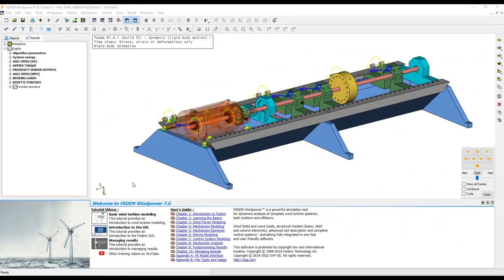When the FEDEM model is benchmarked and optimized for maximum simulation performance, then you can prepare it for digital twin simulations. And then you got several options. If you're familiar with Python, you can use the FEDEM PyScript or API to run FEDEM from your own Python script, which might have user interfaces created in an app like Streamlit in order to visualize curves, 3D animations from the FEDEM simulation in a web application.